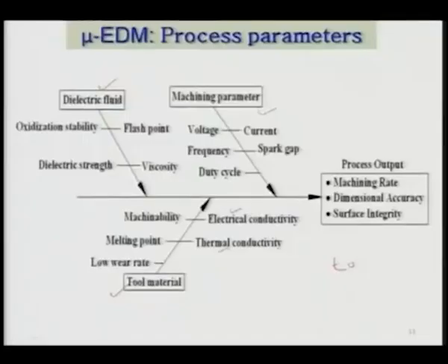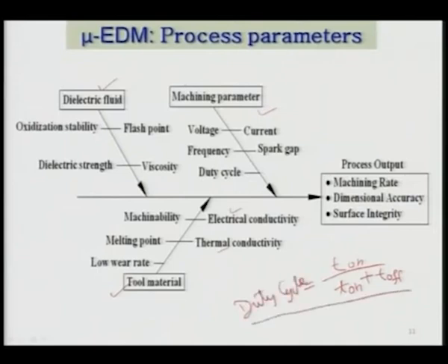And then duty cycle, that is nothing but T on, that is the on time of the pulse, divided by T on plus T off, that is the on time plus off time of the pulse, that decides the duty cycle. And this plays an important role in case of EDM as well as electric discharge micro machining.